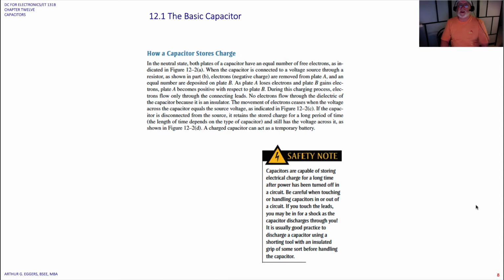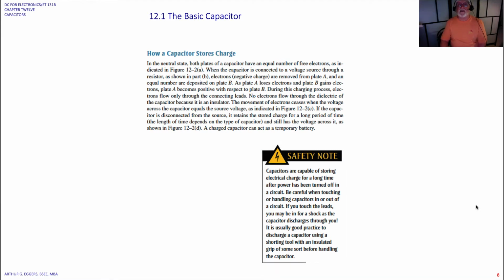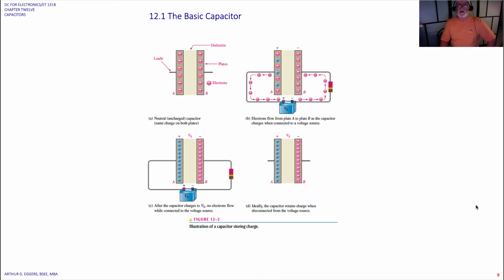So capacitors are capable of storing electrical charge for a long time after power has been turned off in a circuit. So you must always be careful when touching or handling capacitors in or out of a circuit. If you touch the leads, you may be in for a shock as the capacitor discharges through you. And there are a lot of high energy devices like power supplies that have huge capacitors in them. And the whole idea behind that is for them to store energy.